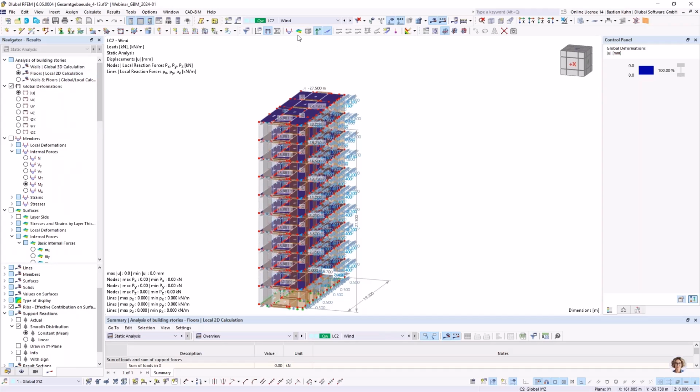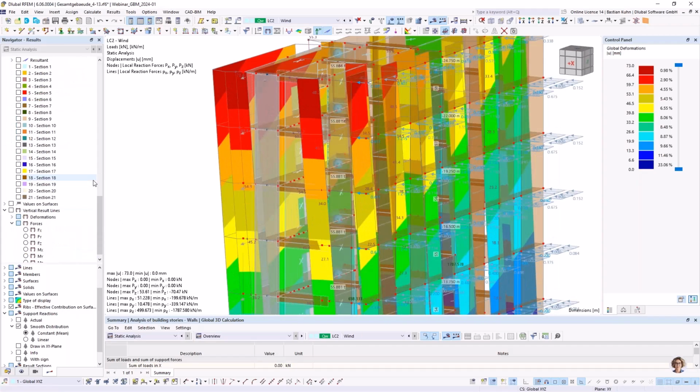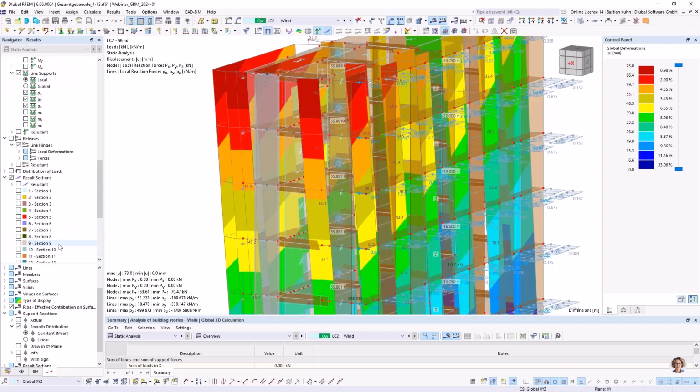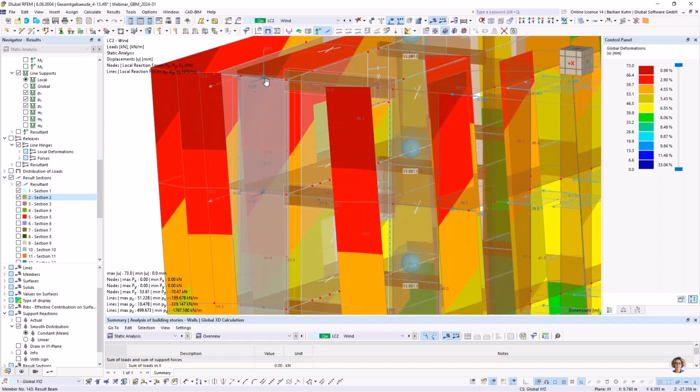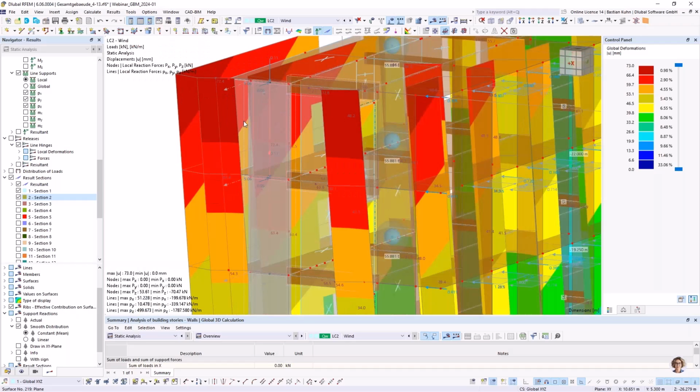When we take a look at load case 2 and the wall, and maybe also the resultant, that would be something where the shear walls that I defined play quite a big role, and we're looking for section 1 and 2, because you see that in here you have the horizontal force of 5 kilonewton in total that goes through the wall, and here are introduced as a new loading to the story underneath. So this is how the load transfer in this add-on works.